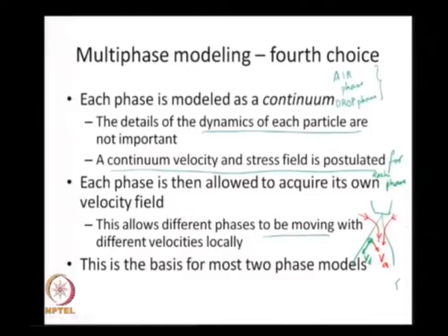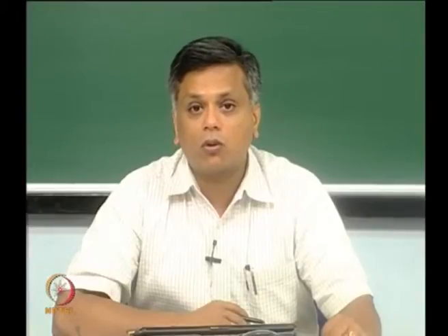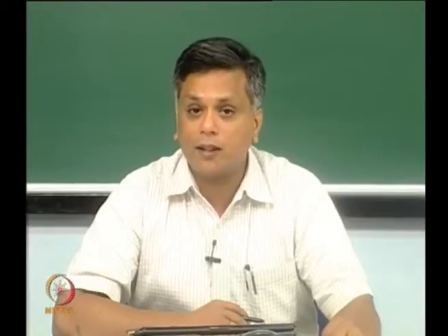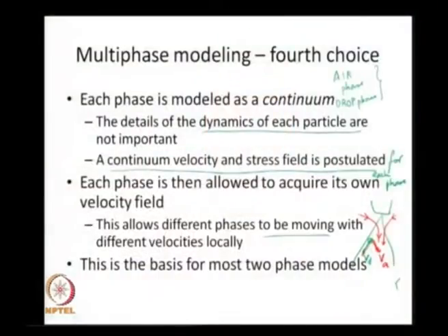The air at this point may want to come in towards the middle of the spray, but the drops may want to go in a slightly different direction. In our locally homogeneous flow assumption underlying the mixture model, we are not going to be able to capture these two distinct velocity fields, we are only going to get a mixture level velocity field which may look like that.